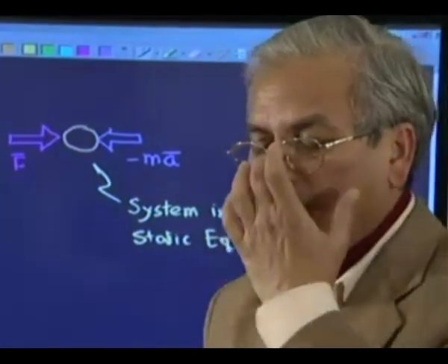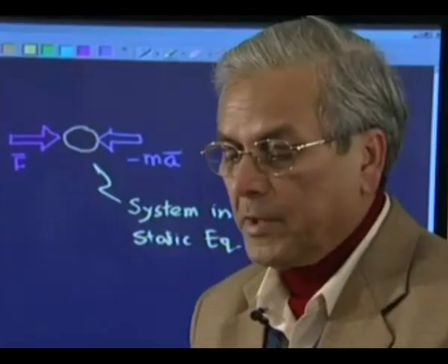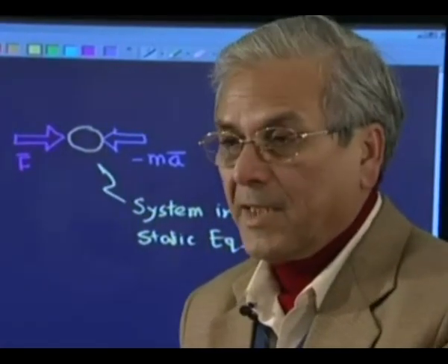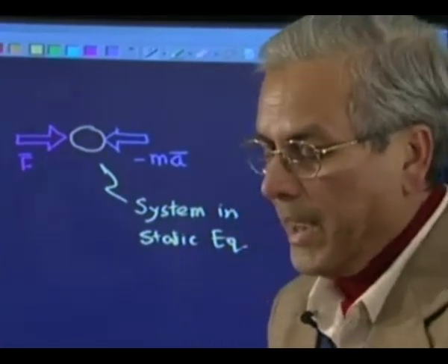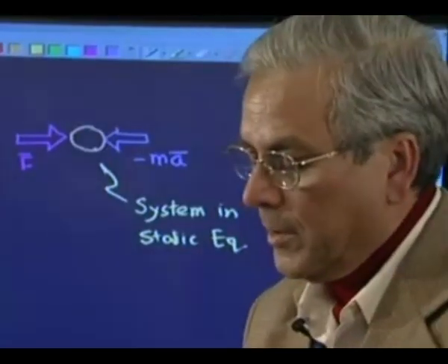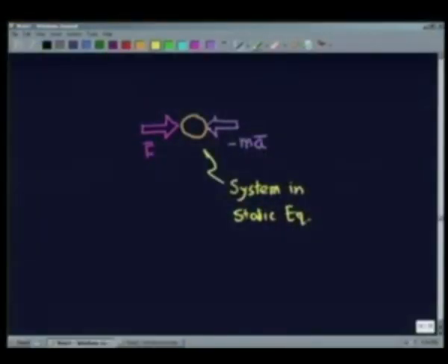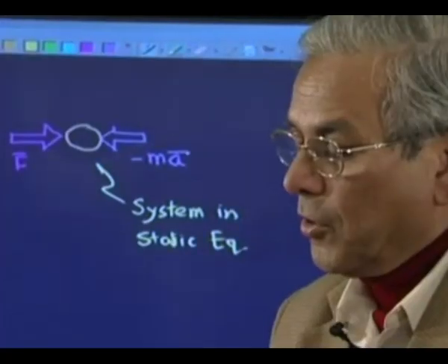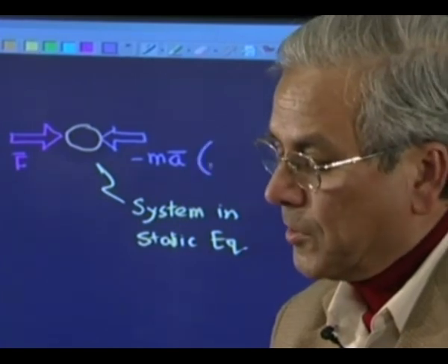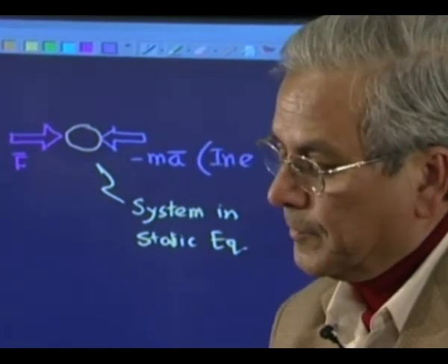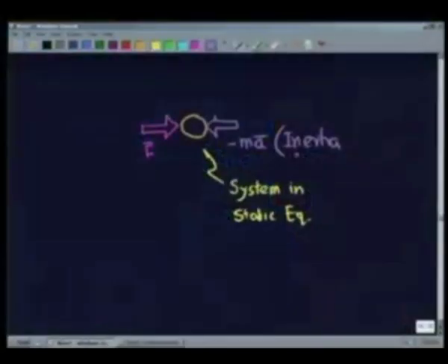So this is D'Alembert's principle, though it is not as trivial as it sounds. It says that if we subject the body to the actual external force along with a hypothetical force, which is nothing but minus m into a, which we call inertia force, the body will be in static equilibrium.